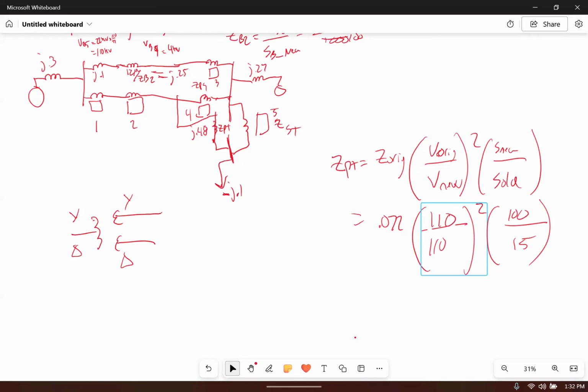Is that because the textbook shows a buried tertiary? No, it's a regular auto transformer, is what we're dealing with at work. And like I said, it'll make a fictitious bus in the middle of the transformer. And you have a primary winding side impedance to the fictitious bus, secondary impedance to the fictitious bus, and then the tertiary connection impedance to that fictitious bus. It just inserts a bus in the middle of it.